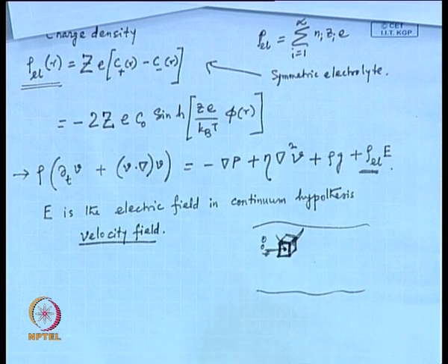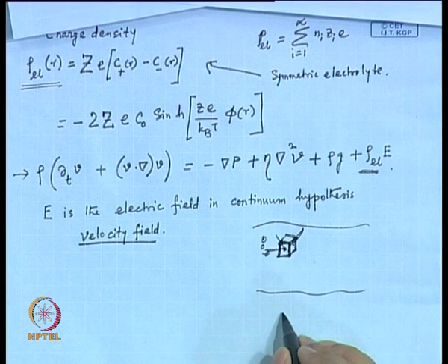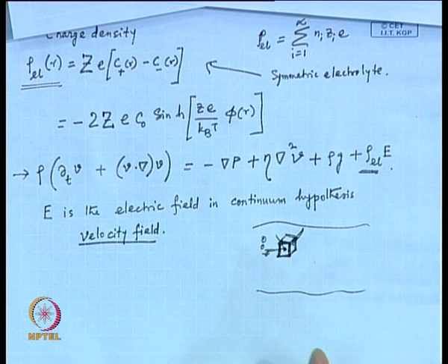When you plot density, or any function, against the probe volume, as you change the probe volume: if the probe volume is too small, you get atomic fluctuations that affect the measurements, and if the probe volume is too big, then the macroscopic mechanism itself leads to a fluctuation. So, your probe volume has to be within certain limits.